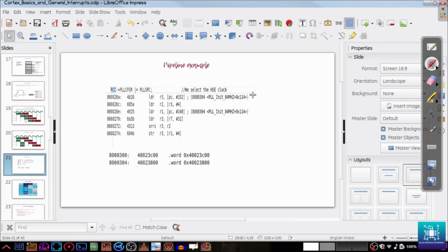to a pipeline that is working in the backend. What generally happens is, if the opcode is not able to accommodate a large number like this, that is, you load some value into the R3 register, and that value happens to be a 32-bit value, then the opcode cannot accommodate that value.